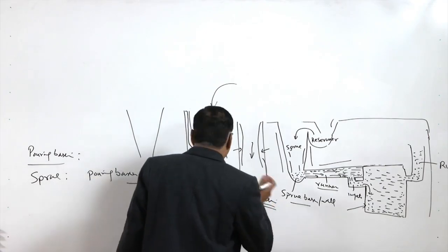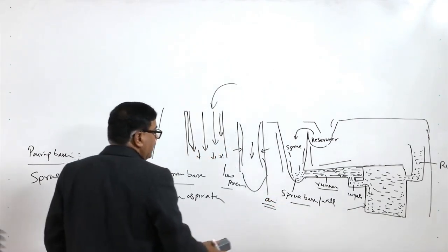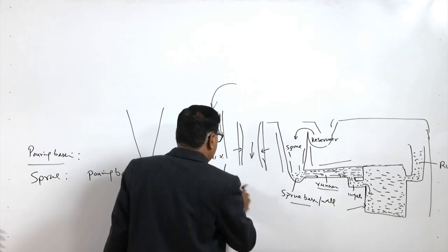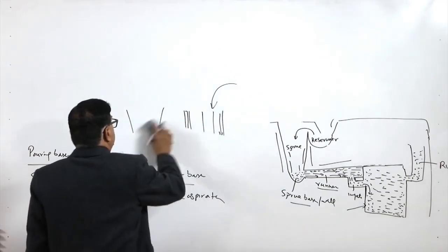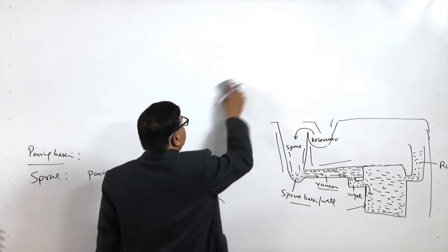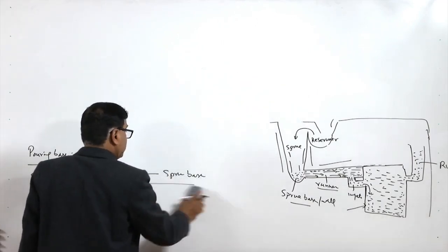This leads to the mixing of air, air pockets and a lot of dissolved air with the molten metal, which increases the tendency for gaseous defects in the casting.